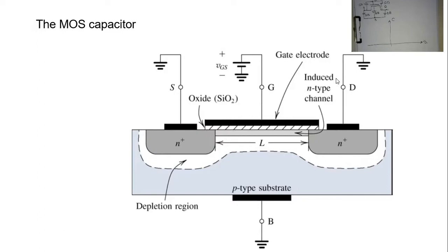Accordingly, in this case, the capacitance will increase due to the depletion region increase. As you know, my dear students, the capacitance effect in the p-n junction is more and more significant whenever you have a reverse bias condition. So this reverse bias drain body capacitance will be more significant with respect to this source body capacitance.